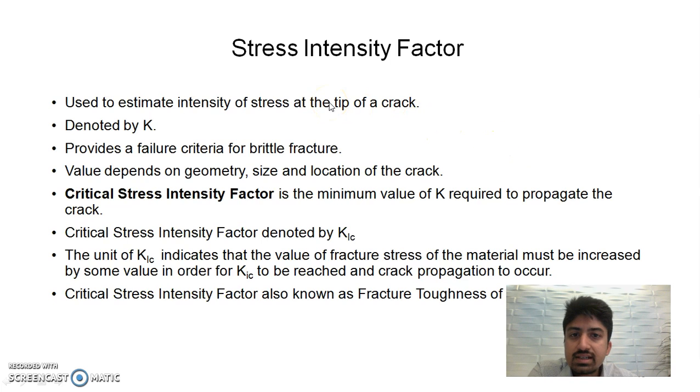So stress intensity factor, as I was saying, the SIFS shown in Workbench is the stress intensity factor. Stress intensity factor is used to estimate the intensity of stress at the tip of a crack. It is denoted by K. And stress intensity factor provides a good criterion for failure, specifically for brittle fracture. But the value of stress intensity factor depends on some factors like geometry, the location, the coordinates of the crack.